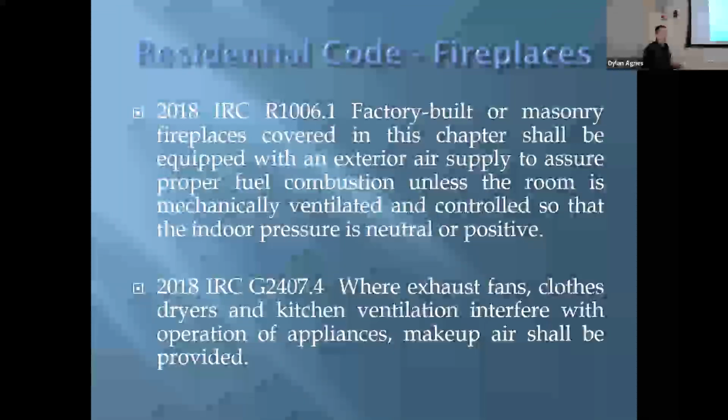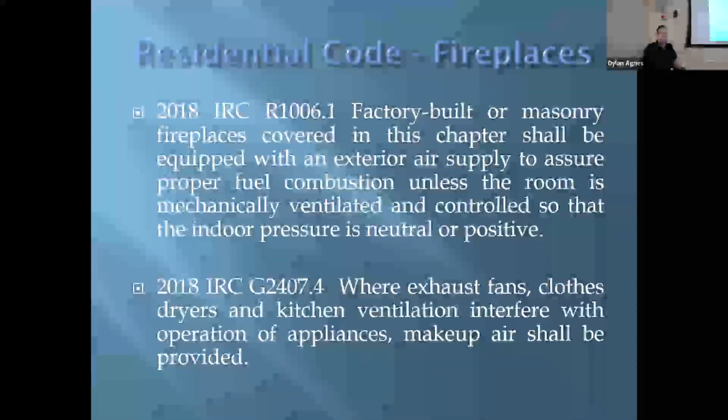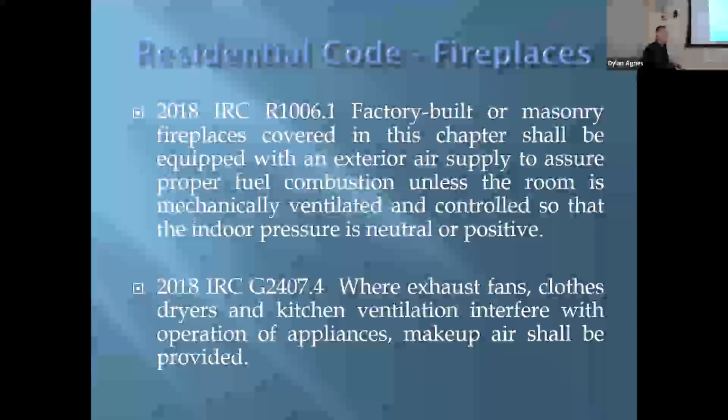Yes, and to give you an idea of what that pressure is, I did all of the homes in Meridian over an extended period of time. I did almost 100 homes, and they ran between -9 and -12 pascals with the exhaust running with no dryer.